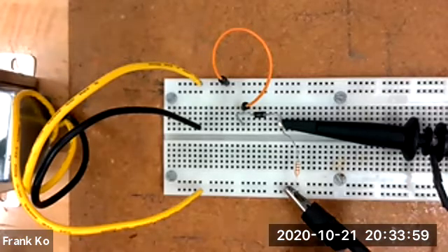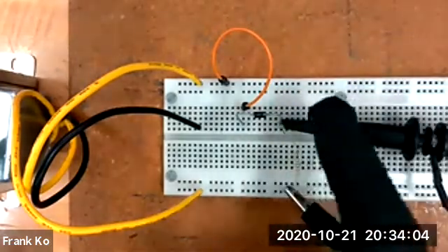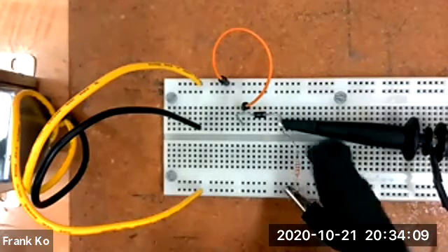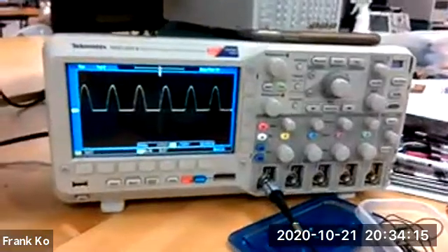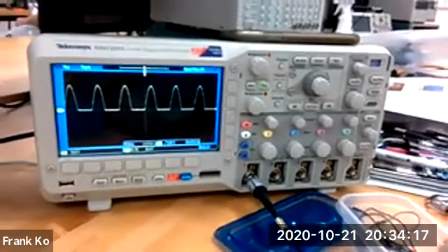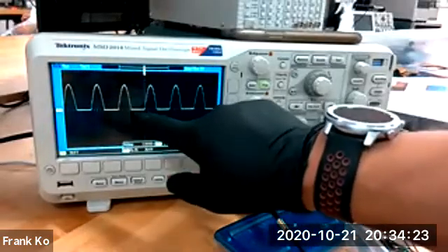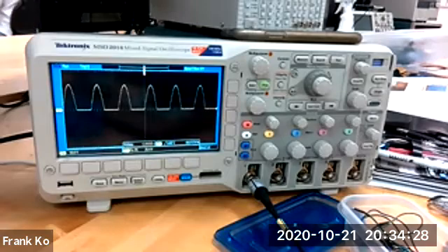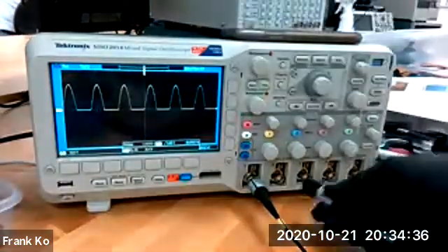And so our probe is connected to the output of our rectifier, between the top of the rectifier diode, or top of the resistor, and ground. We're measuring the output, and the output appears on our display as half wave pulsating DC, meaning we have a pulse and a flat spot, pulse and a flat spot. Now this is called half wave for a reason. So we're going to get another oscope probe. With your next oscope probe, plug that in, if you would, into channel 2.